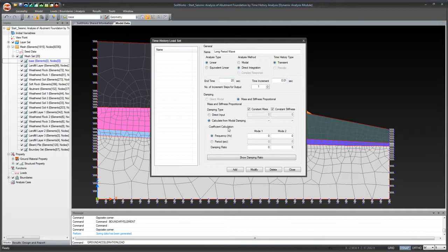And then modal damping, which we'll input manually. For the frequency, let's make it 1.7897. I'm getting these values from the tutorial that was provided; I gave you all a copy, so you can look into it further afterwards. These are the default values assigned by the tutorial. Depending on the wave you're using, these modes will differ. The second default value given is 3424. And then the damping ratio, which is the same for both modes, is 0.05.